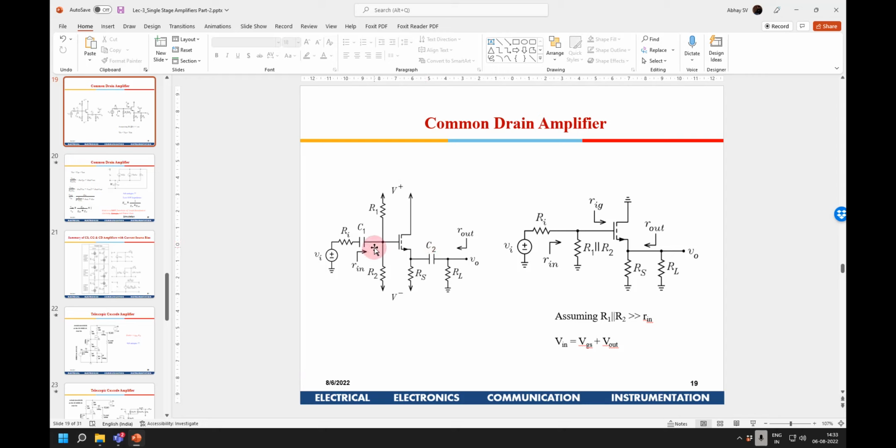Understood? Yeah, but that control we can do by the first stage itself, right? Correct. But for deciding the DC operating point, when we talk about multiple stages, for each stage there will be some specific requirements. Your gain might be one target. But there can be situations where the design requirement of each stage will be slightly different, and you might want to operate at different operating conditions. In that case, you can use the resistances, not necessarily.